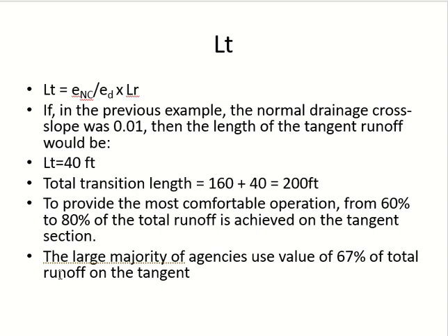Okay, this is better for the understanding of the driver that a curve is coming and he gets prepared. So anything between 60 to 80% is fine. The normal practice is 67%, which is around 2/3. So 2/3 before the curve and 1/3 on the curve. But this is for the sake of the driver, for the comfort and understanding of the driver. The ideal situation is we should do it before the curve. The whole thing should be done before the curve. Clear?